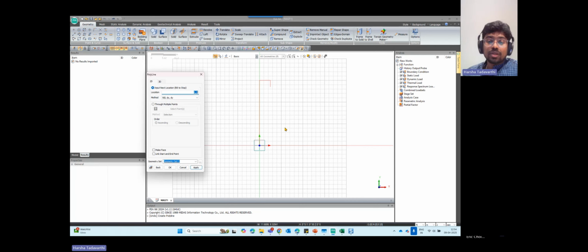So it's 1:1 horizontal to 2 vertical. And then I calculated the values, which will be 13.5 in X direction, comma, and depth is 27 meter, minus 27. So input 13.5, comma, minus 27, and press apply.